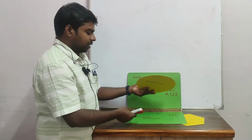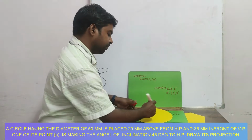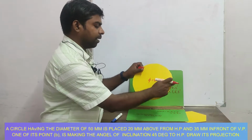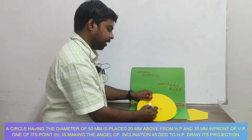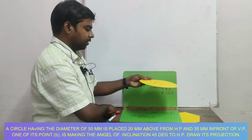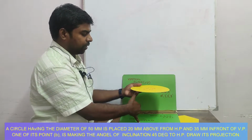So the problem is a circular disc. Let us take diameter of 50 mm. Okay, so d is equal to 50. Let us take the diameter of this circle as 50 mm and the angle of inclination theta is 45 degrees. Okay, and it is on HP, that is 20 mm above from HP.